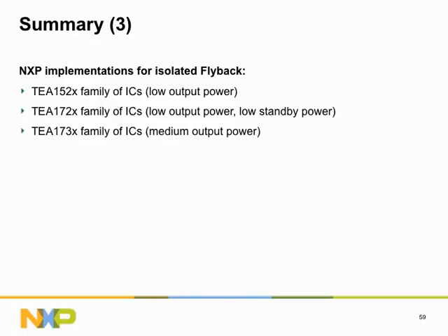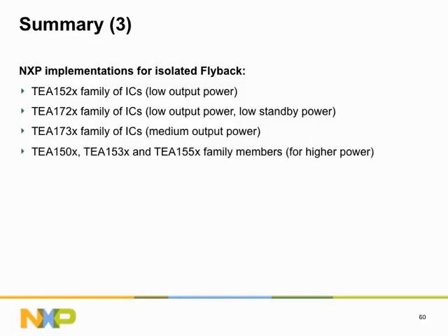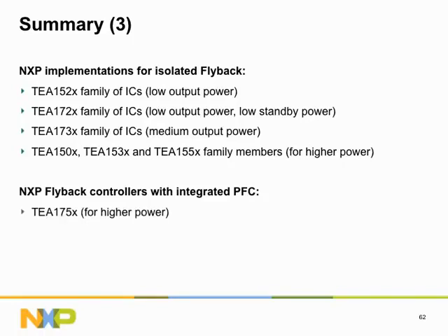This controller IC requires an external primary switch, and the TEA150X, TEA153X, and TEA155X family of ICs for higher output power. All these ICs also need an external primary switch. Finally, there is also a family of flyback controllers that has an integrated PFC stage, the TEA175X series.